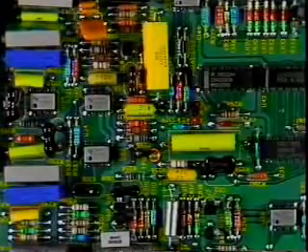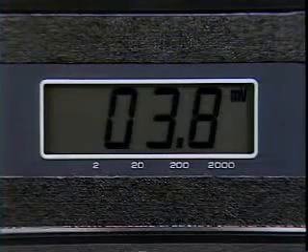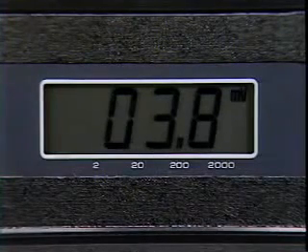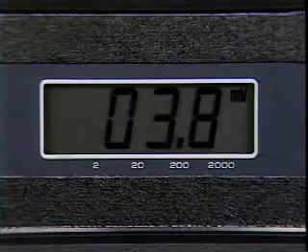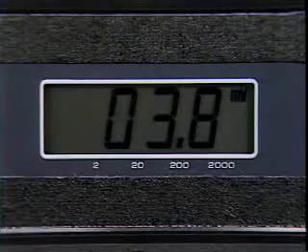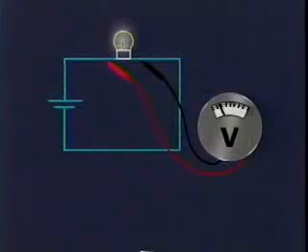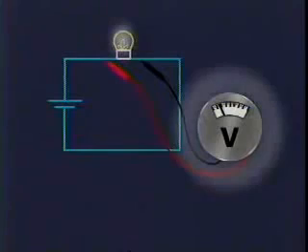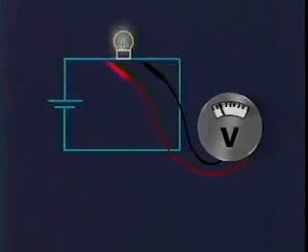When working with circuits which have a very small current flow, the meter can have a significant impact on the current in that circuit. The accuracy of the measurement might be questionable, and a low-quality meter might even damage an electronic circuit. When using the multimeter in its voltmeter function, it removes some current from the circuit in order to operate. If its internal resistance is low, it removes a significant part of the current. If the internal resistance is high, the effect on the circuit will be minimal. The higher the internal resistance of the multimeter, the less current it will draw.